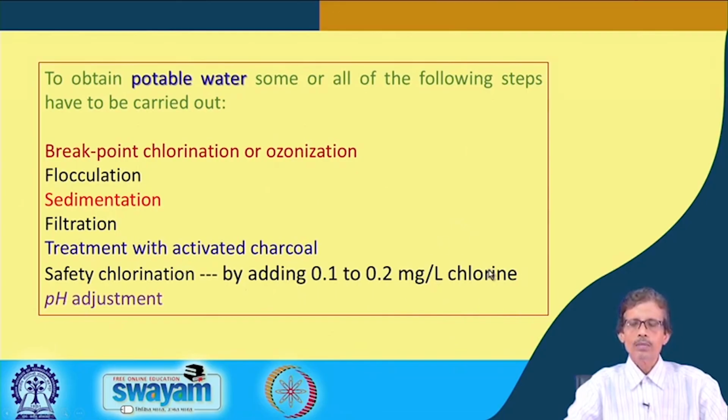The chlorine can react with the hydroxide ions if it is slightly alkaline to give hypochlorites or other active chlorine-based material. So, we should have a very low concentration of chlorine which can only kill the germs, the organic matter, the dye molecules or other unwanted material still present in water.